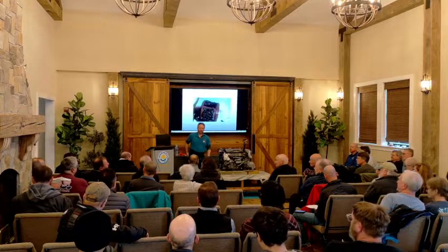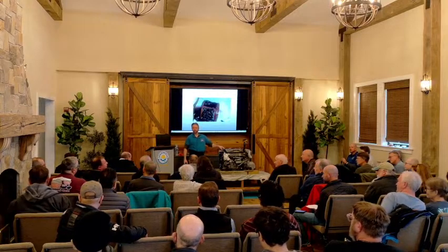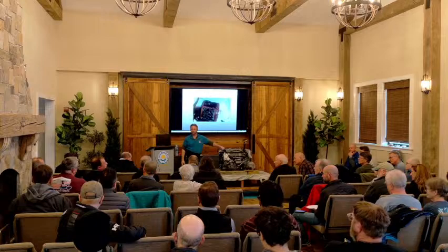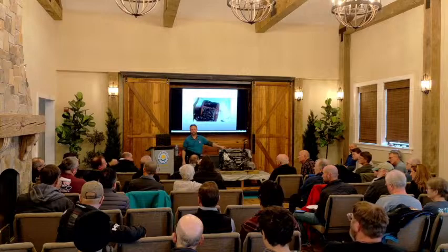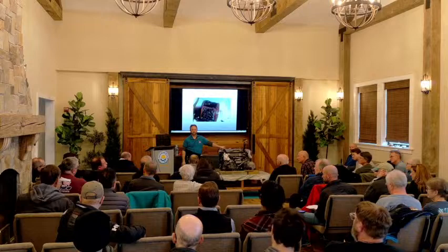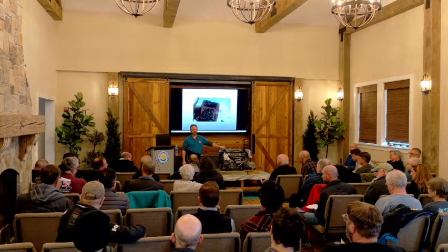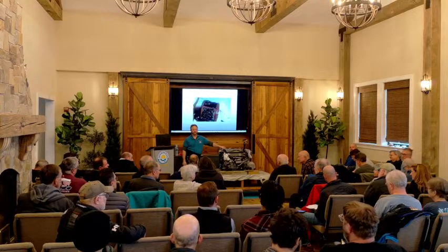I've got folding props because I'm a sailboat and I have to shut it down when I'm underway to fold the props, in gear going forward, so the props will fold. And then I move it and put it in reverse to lock the shaft. Right. But I don't shut it down in neutral except when I'm gear stuck. And it doesn't make any difference for shutting down my engine. Well, I don't have that. I've just got a regular.